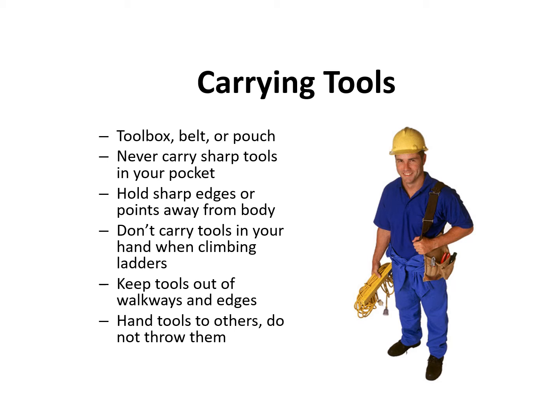When carrying tools, use a toolbox, a tool holder, tool belt, or tool pouch to carry tools in order to protect yourself as well as the tool. Never carry sharp or pointed tools in your pocket. Carry sharp or pointed tools with a sharp edge or point away from your body. Just in case you slip or fall, you will not land on the sharp edge of the tool because it faces away from your body.